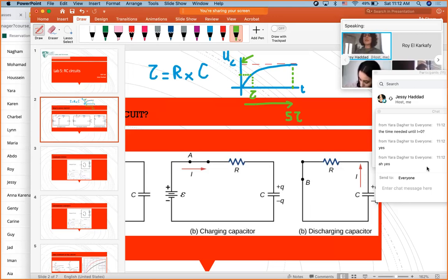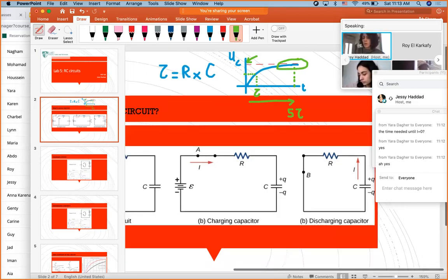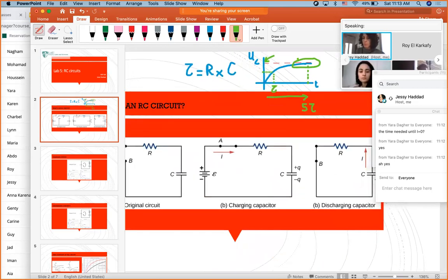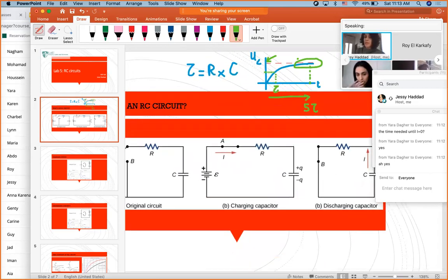However, it's not very practical because sometimes it takes you forever during the waiting process because experimentally things are not perfect and the current may never go to 0, so the behavior at the end of the tail sometimes is weird, like it's not following the theory, because of probably the power supply you're using. So it's not safe experimentally to target 5 taus. Let's target 1 tau only.